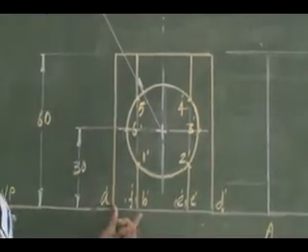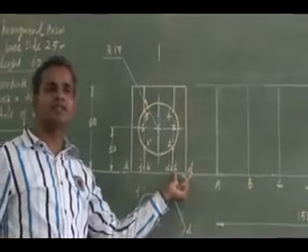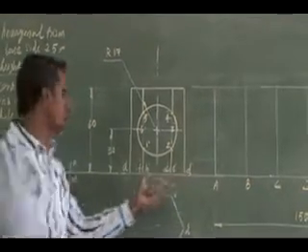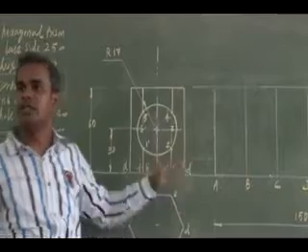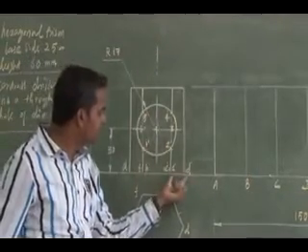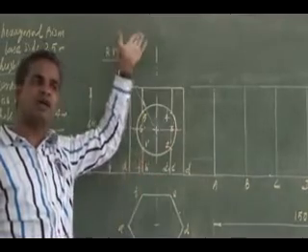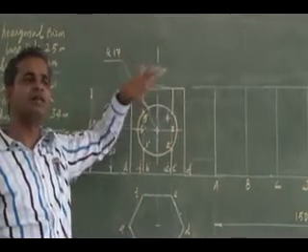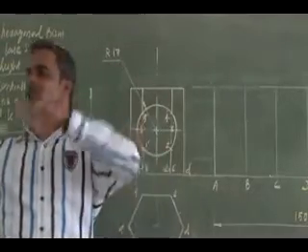The visible faces AB, BC, CD. On those I will have circular cutting points, I have to mark them. Similarly the hidden faces, that is DE, EF and FA, will also have a circular hole. So if I open it, I can see 2 holes in my development.